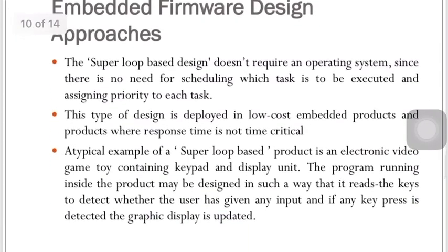The super loop based design doesn't require an operating system, since task scheduling is not required. We know which task has to be executed first, so we write it first in the loop, and it will go one by one. There is no OS required for this super loop, because we are not assigning priorities or scheduling tasks, since the sequence of execution is already fixed. We are not able to change it.